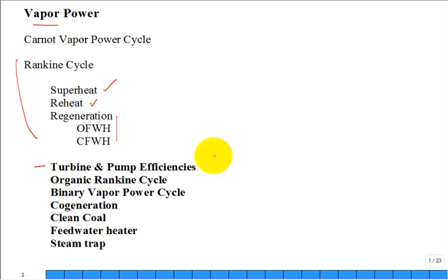This is just a review of what we had in Thermo 1, but we want to talk about it because I've avoided having pump and turbine isentropic efficiencies. Up to this point, I assume they're 100%. So it's reversible expansion through the turbine as well as through the pump. It's just extra steps and extra work when you have the inefficiencies or the less than 100%.